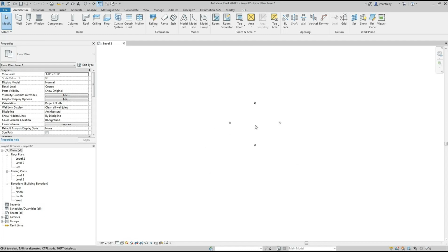This is Autodesk Revit's workspace. I'm using my mouse wheel to zoom in and out. I'm holding my mouse wheel down to pan left and right. So these arrowheads, here, here, here, and here, are actually cameras. Let's call them cameras. They're actually elevation tags. But when you double click on one of these arrowheads, it will launch a camera looking at something in this downward location. Your drawing should be located here in the middle of the screen.